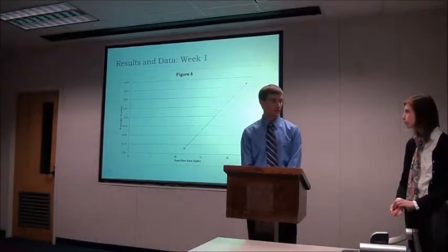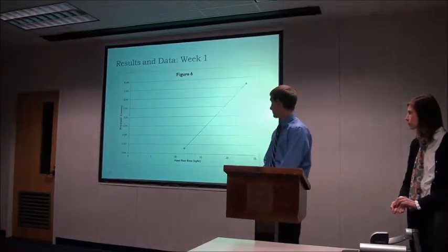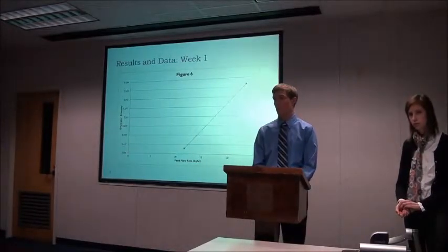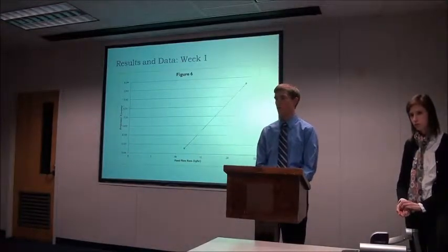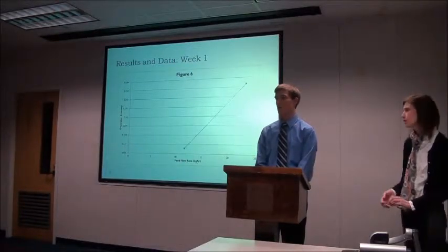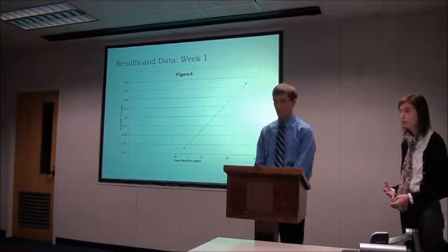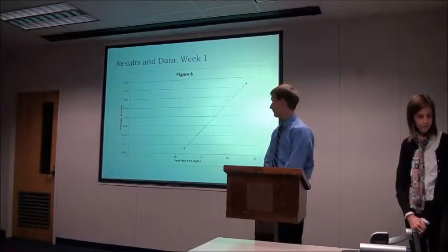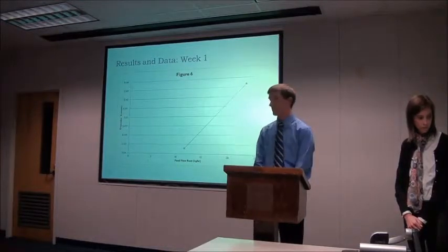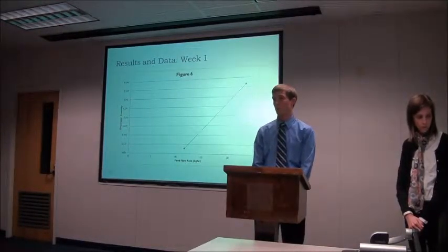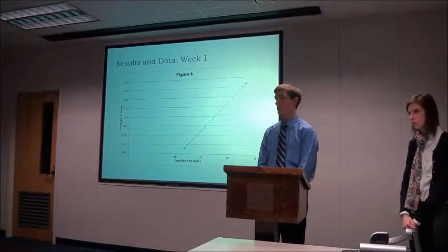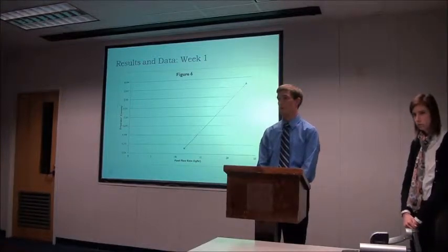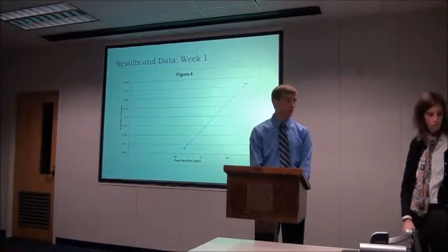From what we were expecting, the economy should have gone up, which it did as flow rate went up, because the economy is the kilograms of solvent vaporized over the steam feed. So in our case, the kilograms of water vaporized per steam feed. Since the steam feed was constant and the liquid flow rate went up, we expected it to go up, because more water was going into the evaporator, allowing it to vaporize more water.